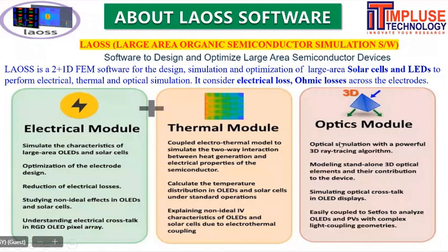This optical module contains a powerful 3D ray tracing module, where whenever rays enter the device, it will capture how the rays are diffracting or refracting, or how much light gets absorbed by your device. So optical analysis, or removing some optical losses, can also be done by using this optical module. The software is divided into modules; maybe you are working on only the electrical part initially, or electrical with thermal as well, or all of them together can also be taken.